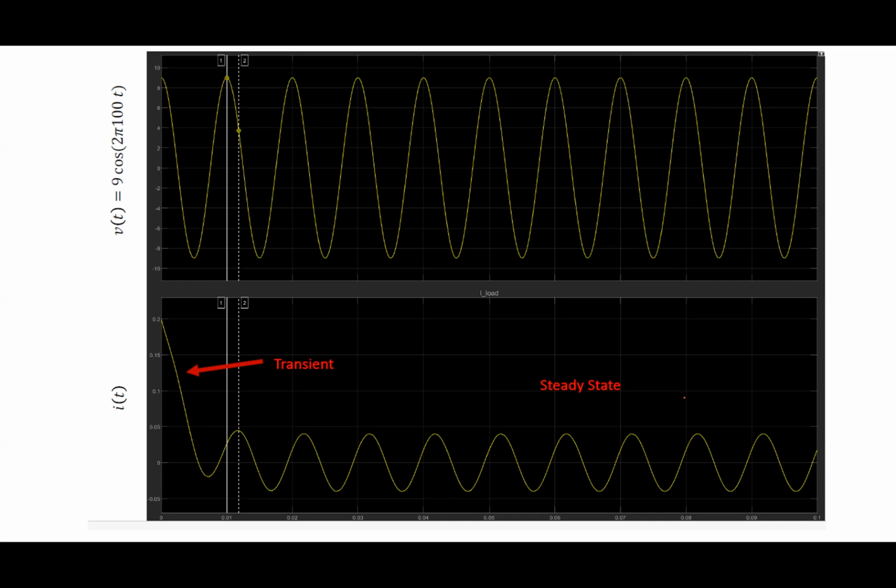There's a transient that's going to happen there, and I got a circuit breaker that has to detect that and figure all that stuff out. That would be a situation where I need to worry about the transient, because the current's going to get bigger or smaller, and there's going to be some transition. This behavior where it's not sinusoidal is really kind of bad for a circuit breaker.